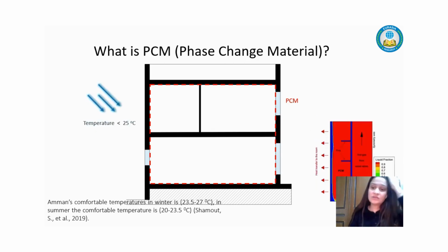And then when the exterior temperature drops beneath 25 degrees Celsius, the phase change material will start to solidify, which means it will change its phase from liquid to solid. While doing that, it will release heat into the interior, stabilizing the interior temperature and keeping it comfortable in the enclosure when the outdoor temperatures are below a certain degree, which means that the outdoor temperature is a bit chilly. Here's an illustration showing how phase change material will change its phase back to solid while it releases its heat into the interior.